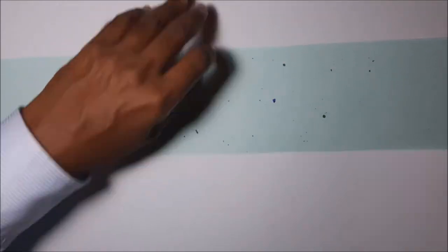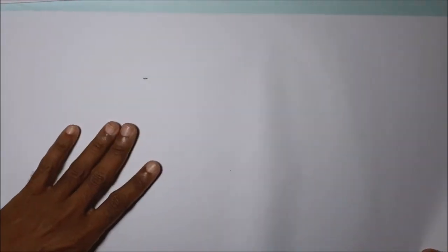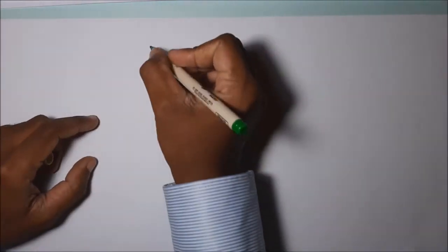Why are we using this sign convention? What is the sign convention? If you take clockwise shearing stress as positive, you have to measure the angle anti-clockwise, and the angle is double. If we take anti-clockwise shearing stress as positive, we have to measure the angle in the clockwise direction in the Mohr circle diagram, and the angle is double.